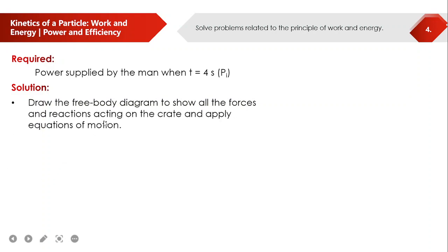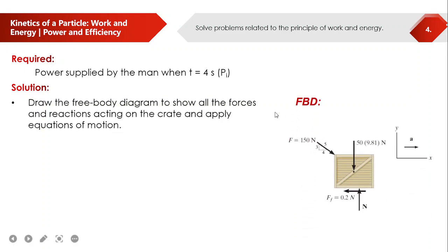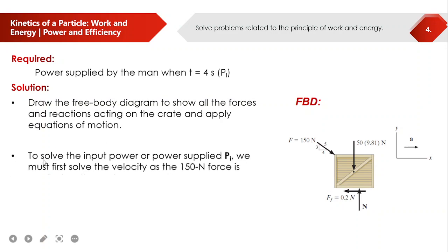Okay, so draw the free body diagram to show all the forces and reactions acting on the crate and apply equations of motion. Ayan, so meron tayong force na in-apply ng man, meron tayong weight ng crate, tsaka normal force because of the weight, tas yung friction force. Kasi meron tayong interaction between the floor and the crate.